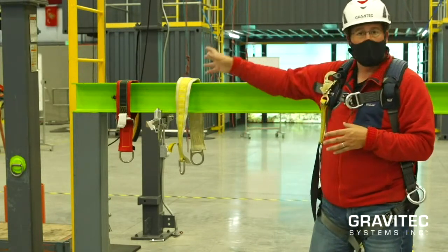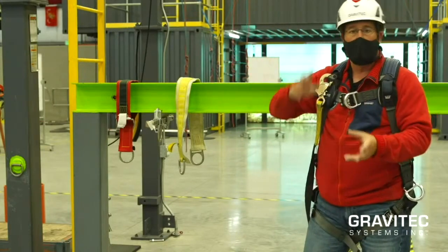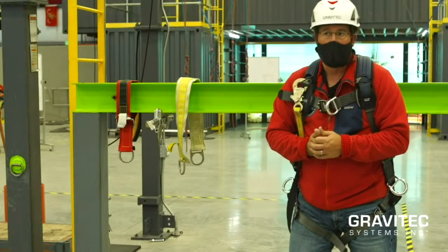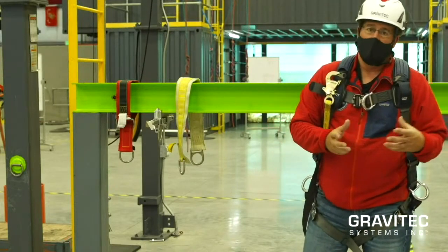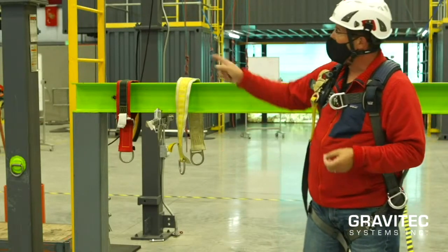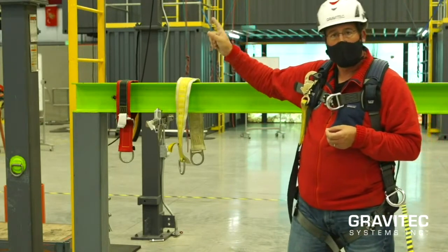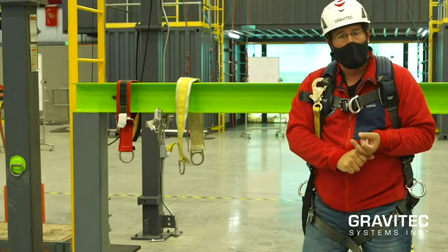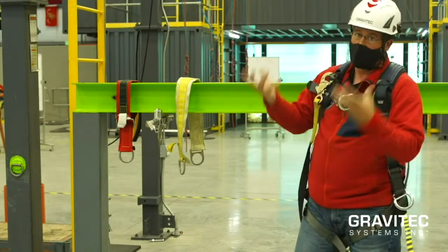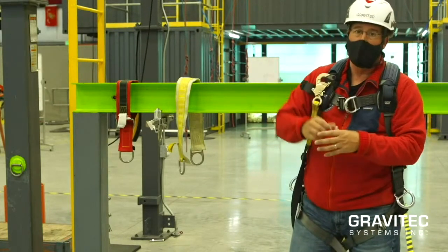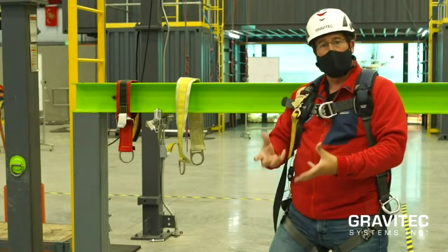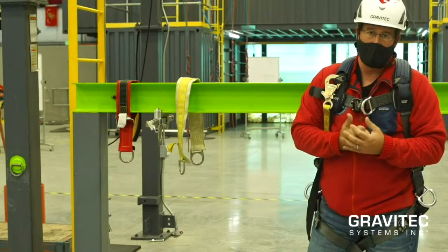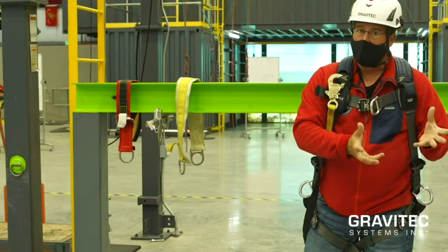So myself looking at that column, I go, boy, it's holding up the building, it's part of my test stand, it's very, very big. I trust it to be 5,000 pounds. Good judgment or not, it's still a guess. The only way for me to determine the strength of that column is to get an engineer, get my steel workbook out, and they figure out what's the existing load on it, is it in compression or tension, and how much residual strength does that column have, and will it support fall arrest or travel restraint loads. That's the only way through engineering.